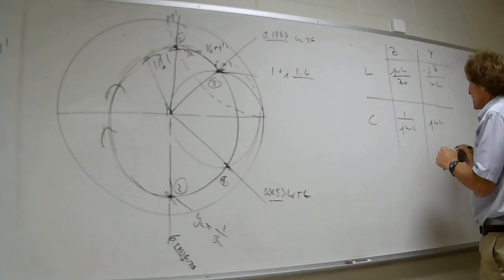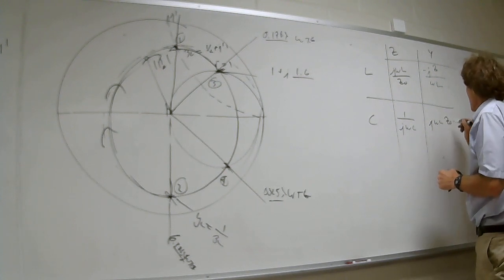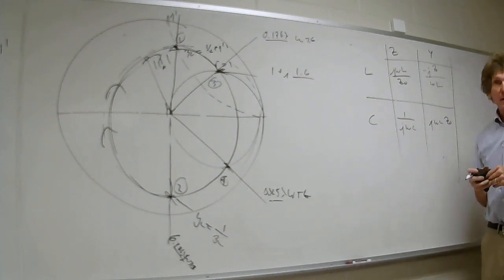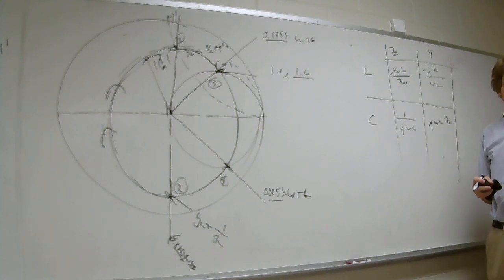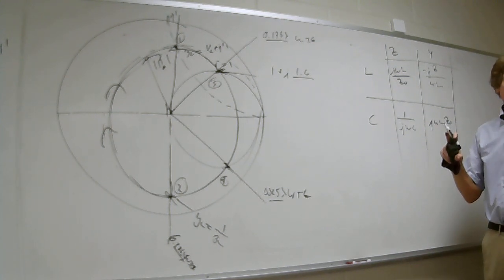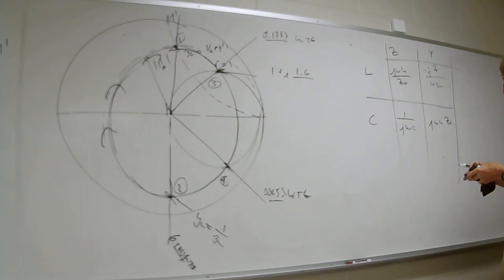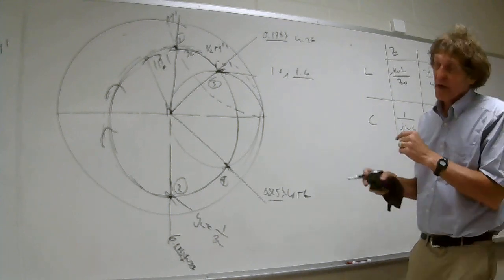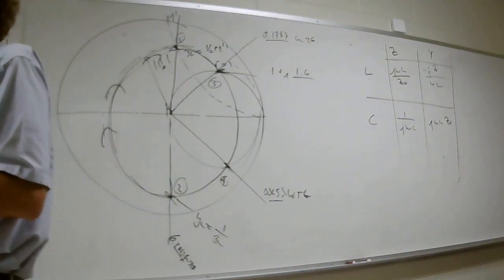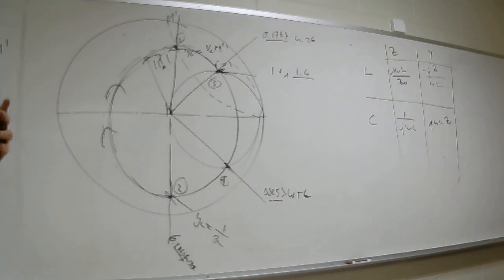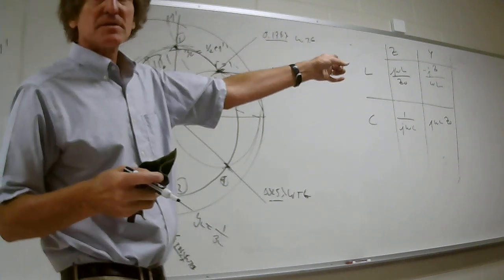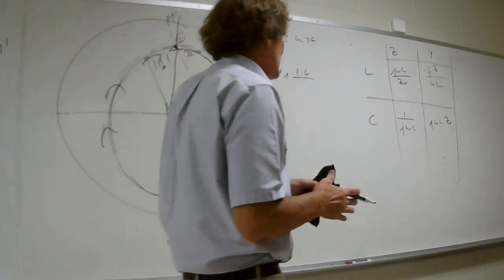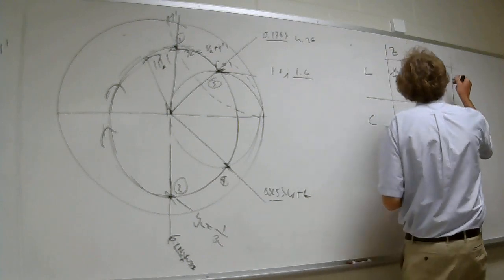Over here, this becomes what? Times Z naught. Everybody with me? Now, it's in parallel. Admittances are always in parallel. That's how you add it. So I have to put that in parallel. I need a value that's got a minus J 1.6 normalized value. That's going to be an inductor, isn't it, class? So I say, this is it right here.